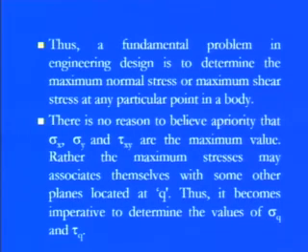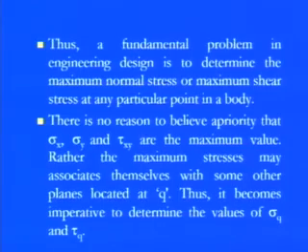Irrespective of whether we are pulling or compressing, they are simply the tensile or compressive forces divided by the effective area. But for tau xy, it is as per the plane. If we are considering the x and y plane, these forces are parallel to the axis, but they do not have the maximum value. So we need to choose the maximum value, as the maximum stresses may be associated with other planes located at angle theta. Thus it becomes imperative to determine the values of sigma theta as well as tau theta.